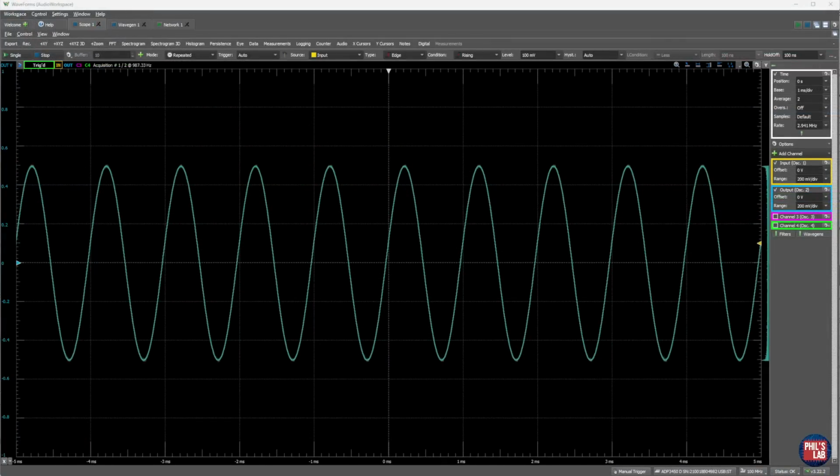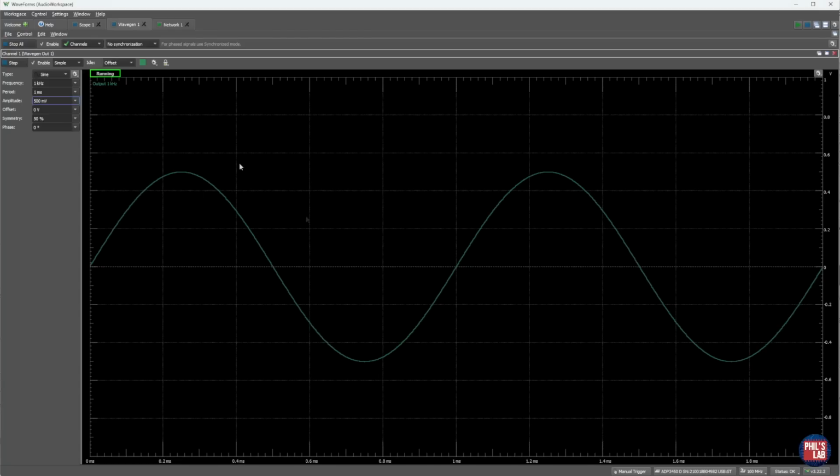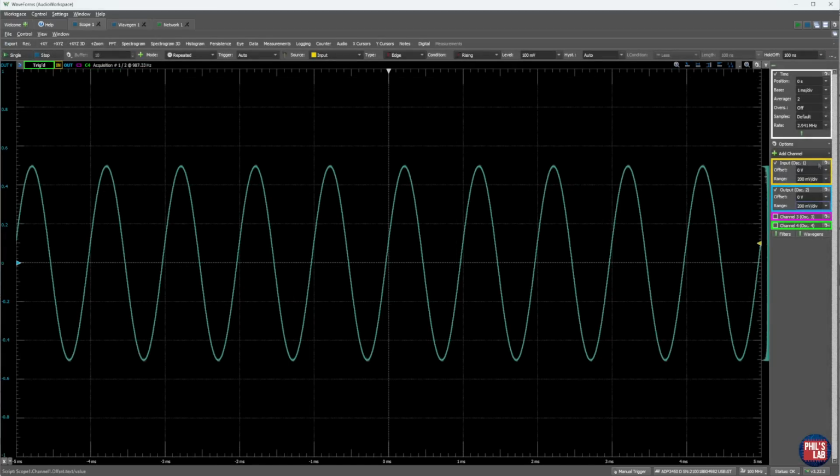We can also examine the all-pass behavior in the time domain rather than the frequency domain, and this might be a bit more intuitive for what's actually happening. Right now I have a wave-gen feeding the input of my digital guitar effects pedal with a 1 kHz 500 mV peak sine wave. I'm monitoring the input with my yellow trace on channel 1, and the output of the pedal at channel 2, which will be the blue trace. Right now I have true bypass. It's a simple connection from input to output, so there of course shouldn't be any phase and magnitude changes.